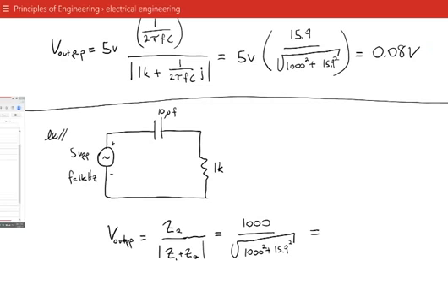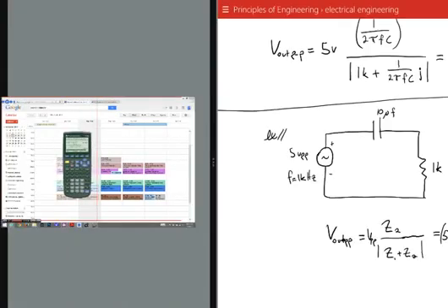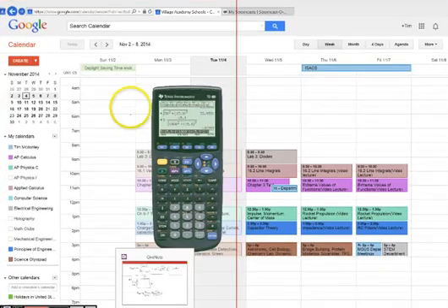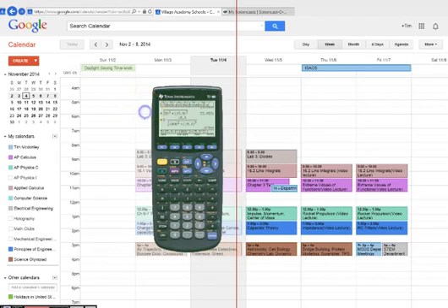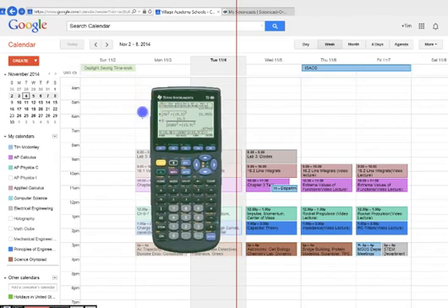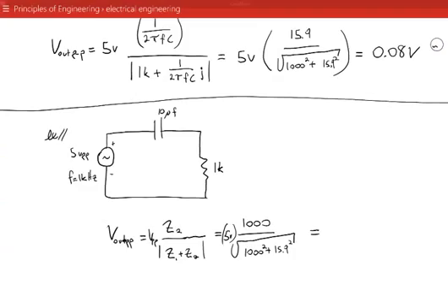And, oh, sorry, I left out the voltage in peak to peak, 5 volts there. Alright, we can calculate that. So really the only difference is the term on the top is not the reactance of the capacitor, now it's the resistance of the resistor, and we're going to get just about 5 volts. So just about everything comes out.